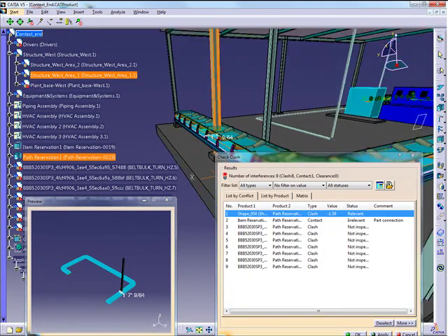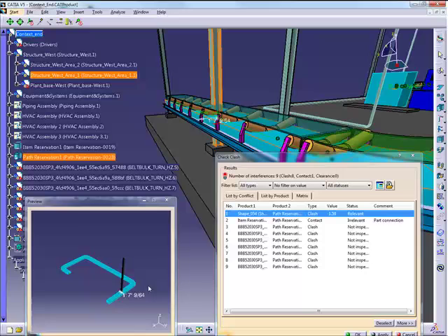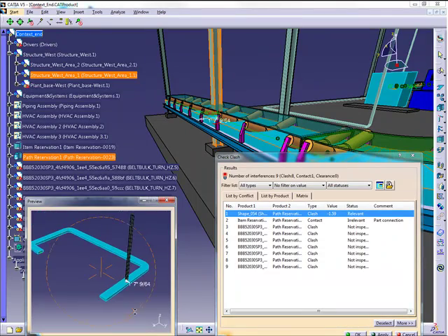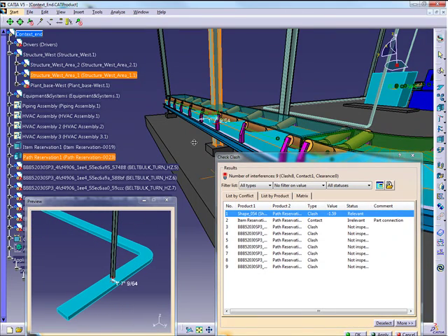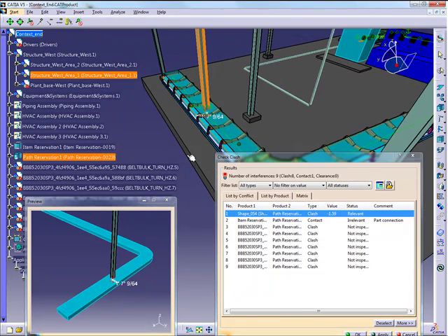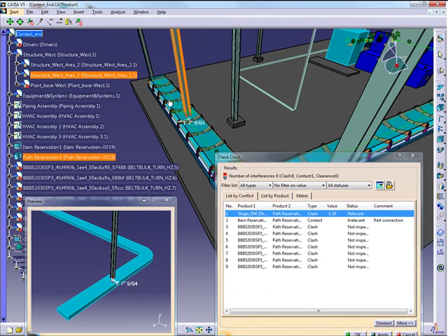And as you can see, the very first one is showing us the column crashing through not only the space reservation, but also the model. So if one just zooms in there, you can see that the column is, of course, going through the conveyor and all these things. So before you get off of this, just note, folks, that every single object being collided with is in the clash detection. We're not going to go through all of them, but we're going to state that this clash is relevant, and we're going to then now labor towards getting this result.